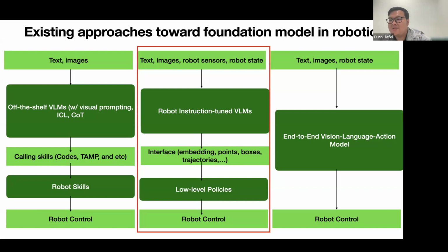So I think by leveraging that to make the high level decision, the idea of driving still stays the same. In this context, driving is like a low level policy. You learn how to drive. It's just that you need to adapt to driving on the left or right. But how to drive is taught to you as a skill that's engraved in you. So in the same concept here, we already pre-train a low-level policy that's good at driving, so your high-level VLM will be able to decide whether you should drive on the left or on the right. I think that will help you save the relearn and unlearn process.